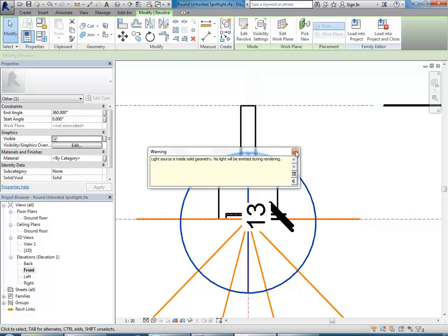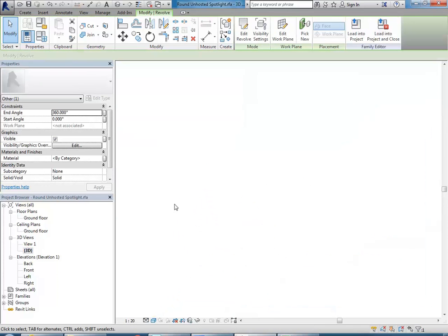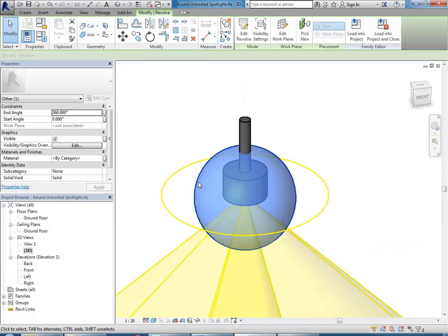Click to finish, and so in 3D, it's given us a warning telling us that the light source is inside this. Yeah, so you need to actually avoid the light source. That's just a set of transparent materials. You can easily just go into a studio light and put a sphere around it. It's really easy. And just make sure that your light material glows but is also fully transparent, or fairly transparent. It doesn't need to be fully transparent, but has some transparency.